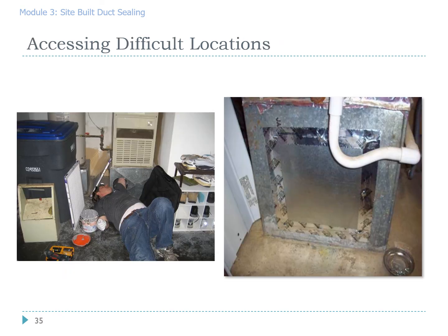This picture shows a duct sealing technician accessing this furnace to plenum connection here. What you can't see are the smaller holes back here. He was also able to seal from reaching in there. This gentleman also attached a paintbrush to the end of a 3-foot stick, applied a lot of mastic in that paintbrush and smeared a lot of mastic over joints. It formed a very effective seal.